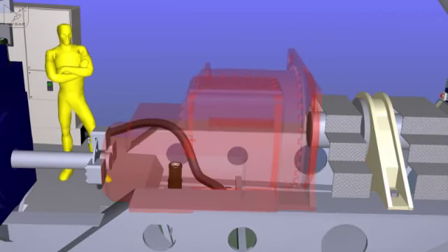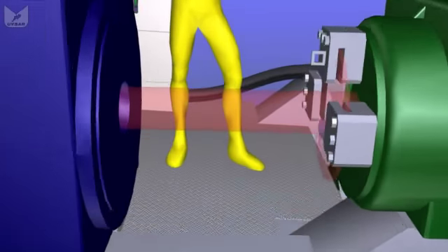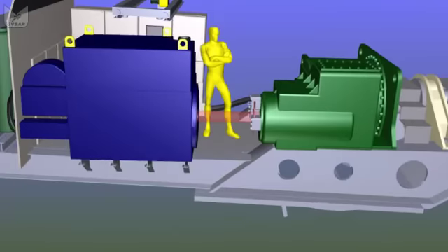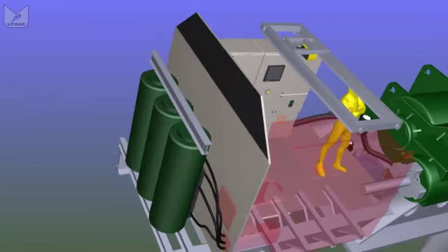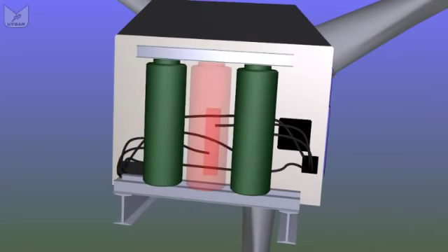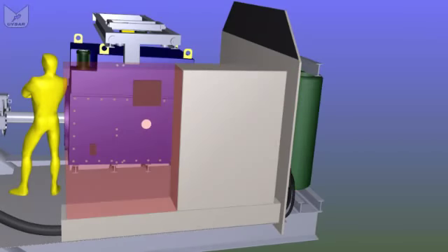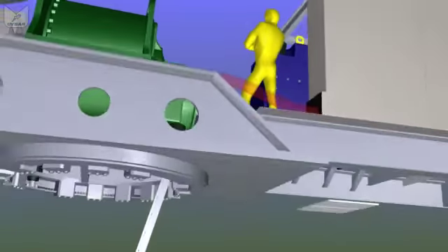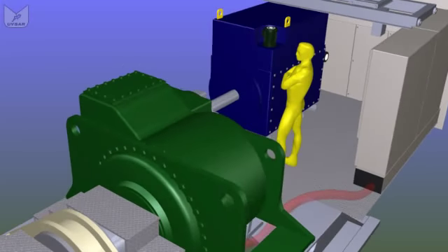So our main shaft drives our gearbox, which is mounted centrally because it's often the heaviest component. Out of the back comes a high-speed shaft, as before. That's where the braking system is. The high-speed shaft then drives the generator, which is usually oil-filled. The generator then supplies 690 volts, in this case into our transformer, which is sitting right next to it. That high-voltage signal then passes through the switchgear and the cabinets, down the dropper cable, straight down to the bottom of the tower, through those switches on platform 2 and off to the substation. And that, as an overview, is pretty much all there is to it.